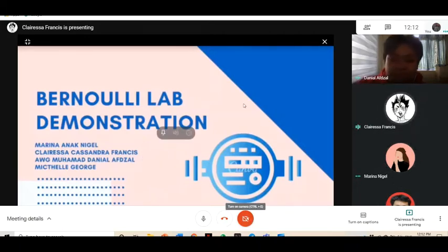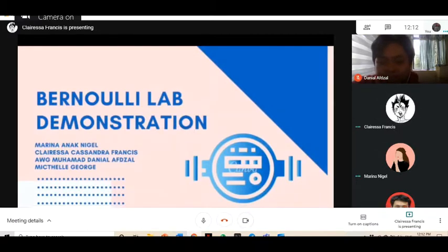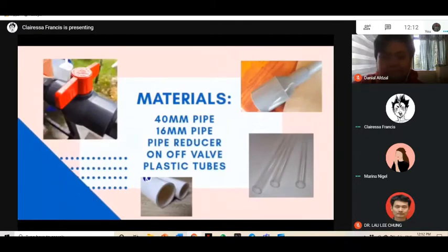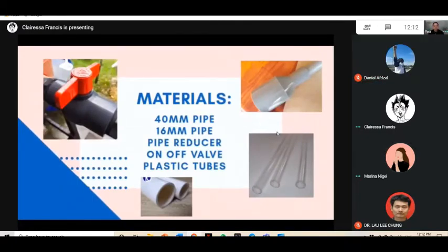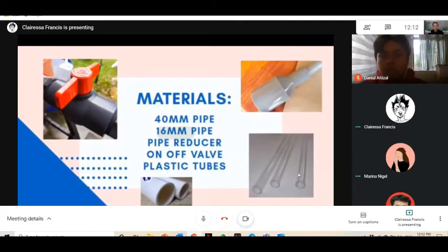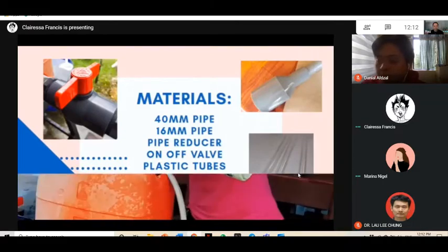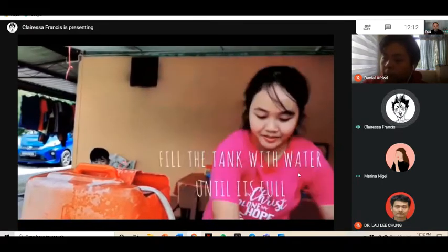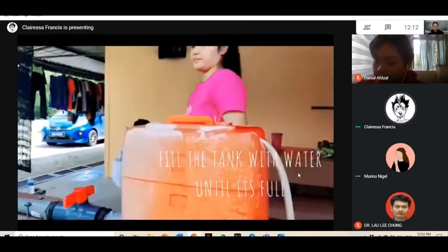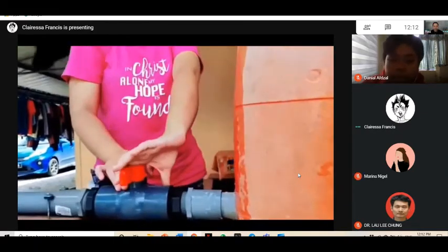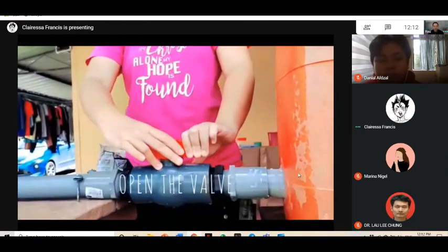Okay. Hello, today I'm going to explain to you about the Bernoulli Theorem demonstration. The materials that we need to demonstrate the Bernoulli Theorem are 40 mm pipes, 16 mm pipes, a pipe reducer, a valve, and 2 plastic tubes. First, we need to fill the tank with water until it's full. Next, open the valve.